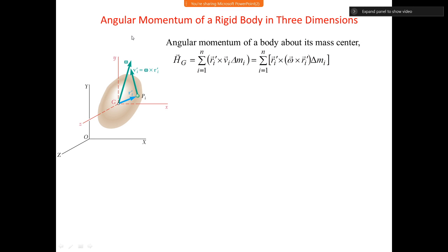When we wrote that equation for a planar object, it was a much simpler equation, and here that equation is going to change quite a bit. So let us first of all study how we express angular momentum for a 3D object. Angular momentum, as a fundamental principle, is r cross linear momentum, the moment of linear momentum. So r cross mv is your basic definition, and again the basic definition of a rigid body is that it is a system of particles put together, rigidly confined. So the basic definition is the same.